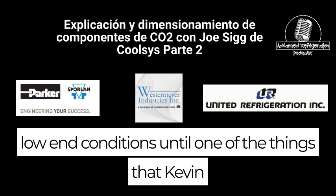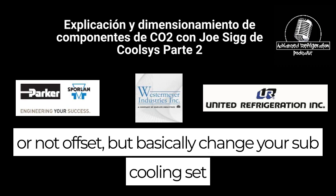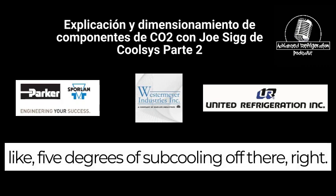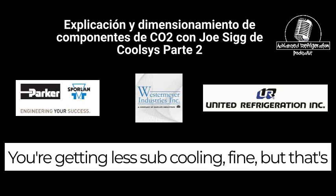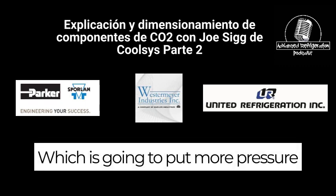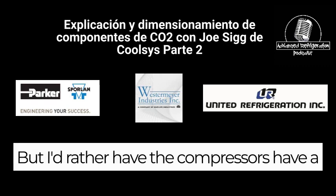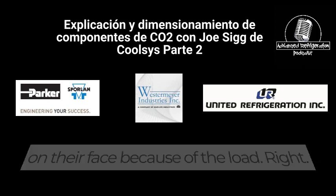One of the things that Kevin and I were talking about is if you could change your subcooling set point on your 326, your iPro. Typically most of these are set for about 5 degrees of subcooling. If you turned it down to 3 degrees, you're getting less subcooling, fine, but that's going to open up your HPV more, right? Which is going to put more pressure on your flash tank, which inadvertently would put more load on your medium temp. So you're robbing Peter to pay Paul, but I'd rather have the compressors have a solid load than not be as energy efficient as they could, because they're already falling on their face because of the load, right?